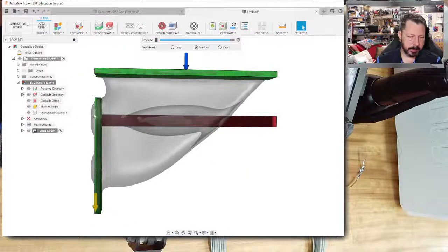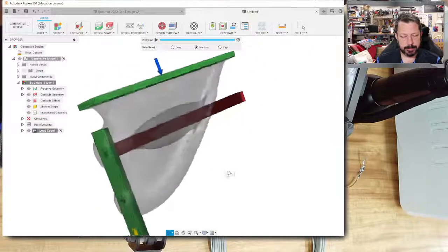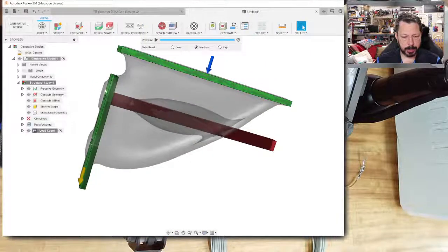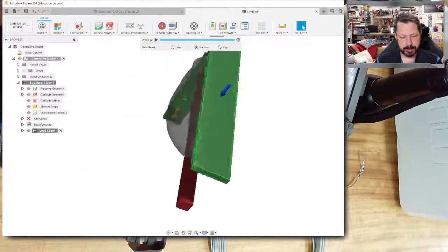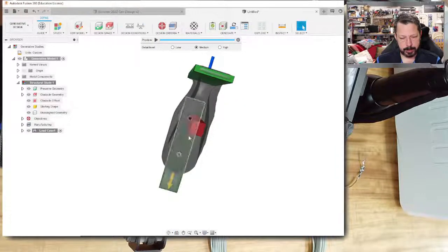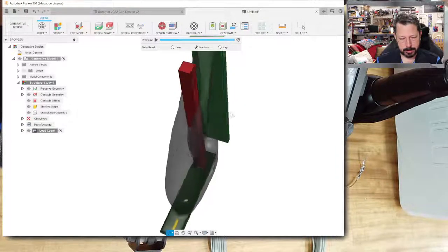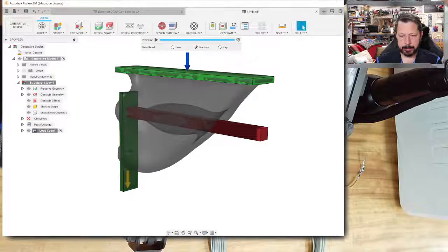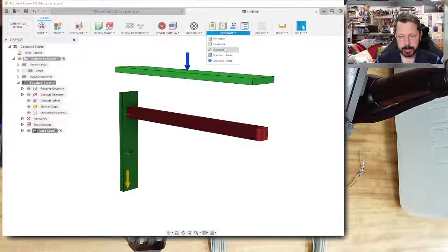Now apparently it's going to put these large bulges on the back over here, which you're going to have to cut off, because we didn't put a blocker back there to keep that surface flat. But you can kind of see how it went around the blocker there. And you can say, okay, we can go with that. Then we can stop the previewer. You go to Generate.